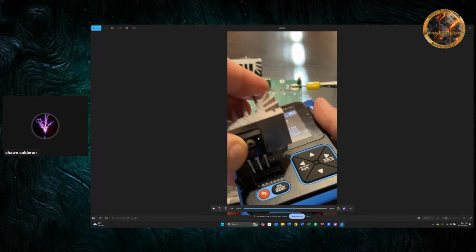If you just screw the MOSFET to an aluminum heat sink, the heat sink won't work very well. It just won't. Your MOSFET will still die. What you need is either a conductive grease or these little silicone pads.